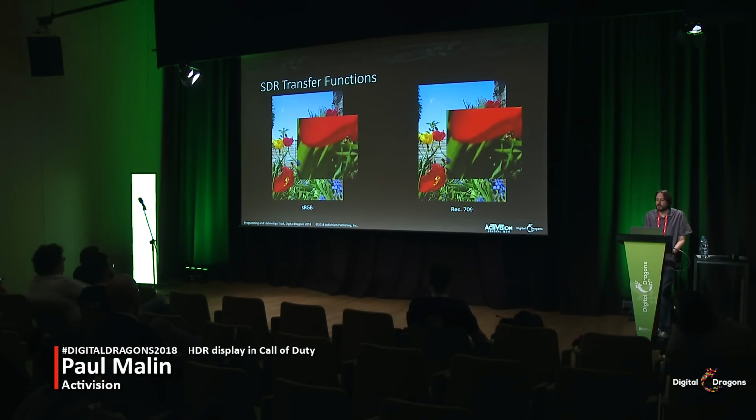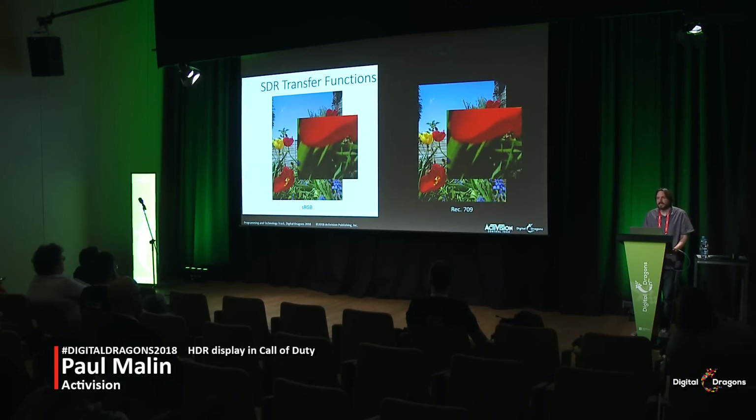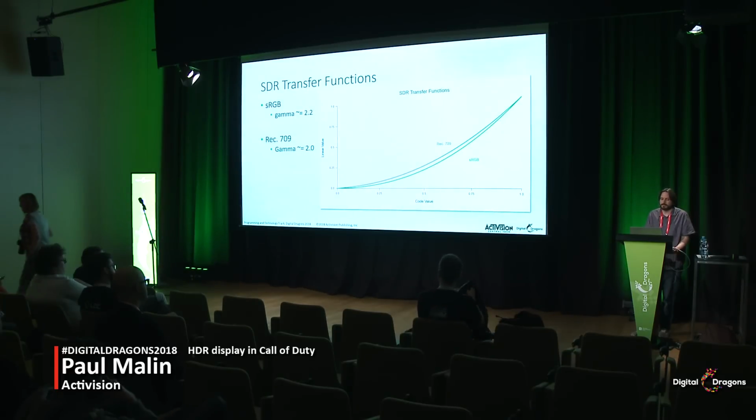So why are there these two different OETF functions, ostensibly for PC or TV displays? And what's the EOTF function that the displays actually use? Well, sRGB is intended for viewing on a PC, which is generally in a well-lit office where there's lots of ambient light. And Rec 709 is intended for home theatre viewing, where the background lighting is dim. The different gamma values are just recommendations to account for this.